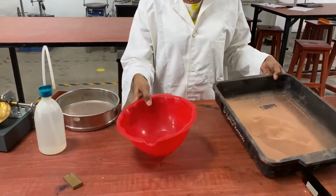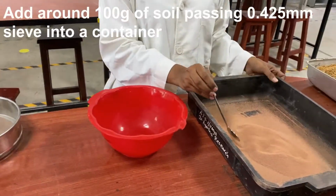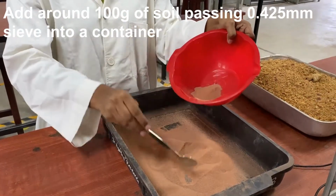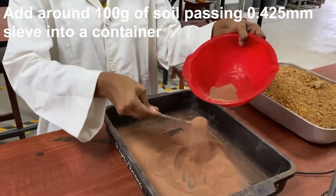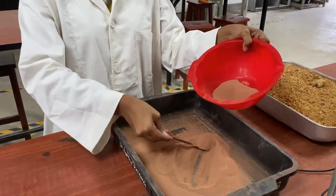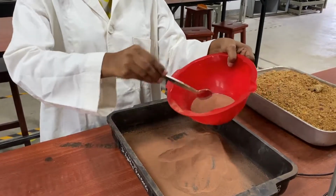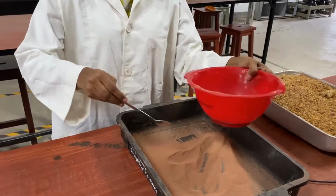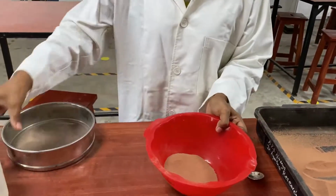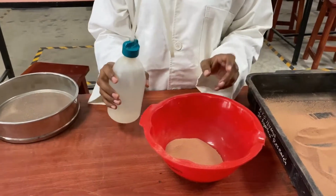We have taken a different container, and we will add around 100 grams of the soil sample to it. We need to add some distilled water, which we have brought here, in order to make a uniform paste.